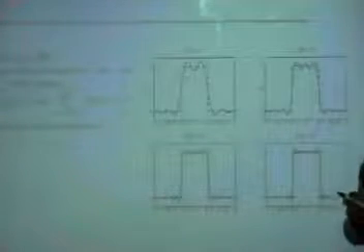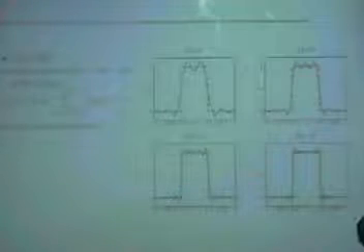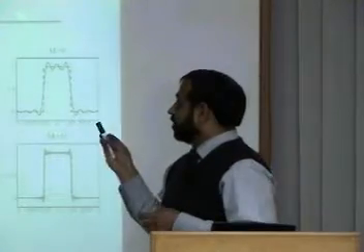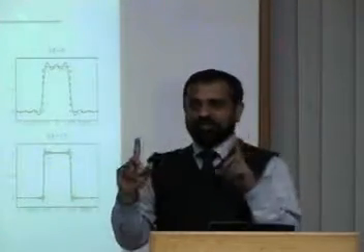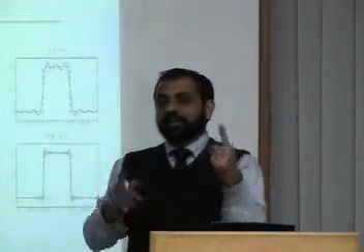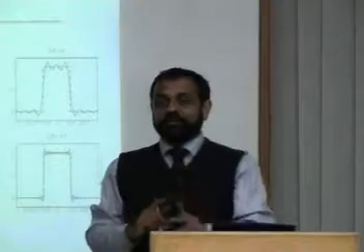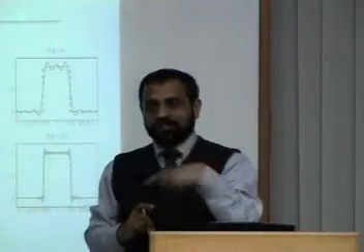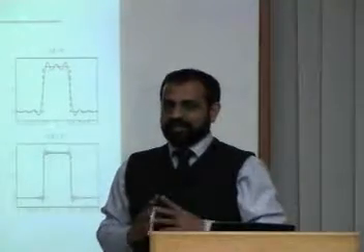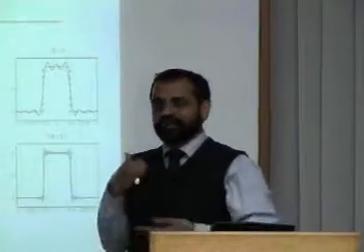This will also create a delay of 35 milliseconds. Oh yes. Ultimately, the buffer size for the main signal will be the double of that. Yes, because the length of this filter is 71. Length 71 means x of n and x of n minus 1, minus 2, minus 3, up to x of n minus 70. That is what you will require to implement this system.